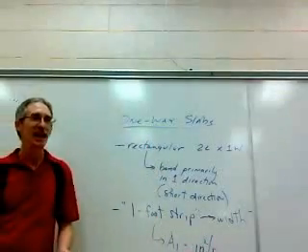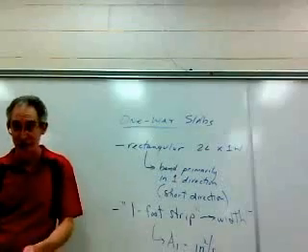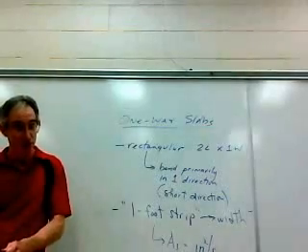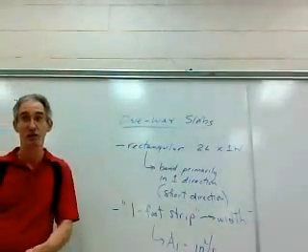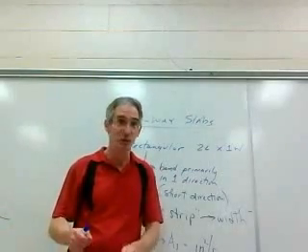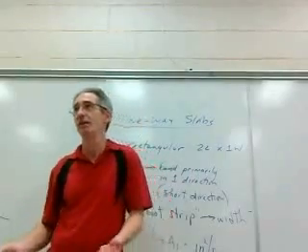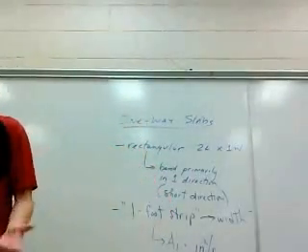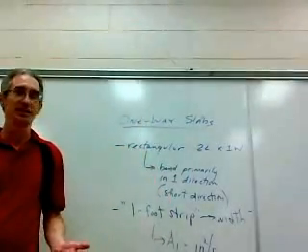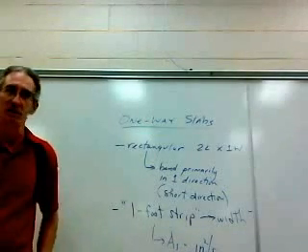When these guys get out to the field, they're not setting these rebar saying, hey, I got to make sure I got 2.3 rebar in this 1 foot. And over here, now I got to my next foot, I'm going to be putting 2.3 rebar in here. Guys out there, they come out and they say, hey, it's 6 inches on center. So let's get my chalk out, away we go.